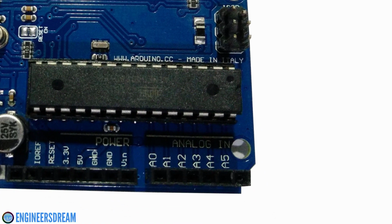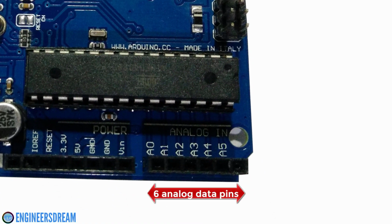An Arduino consists of 6 analog pins which are labeled from A0 to A5, and we can use these pins for connecting analog sensors or analog devices. The analog values that we can plot using the analog pins is in the range of 0 to 1023.